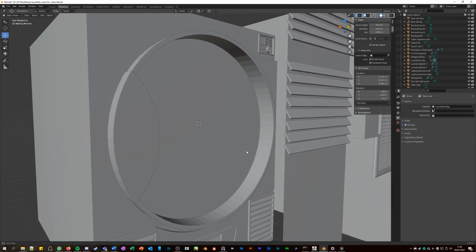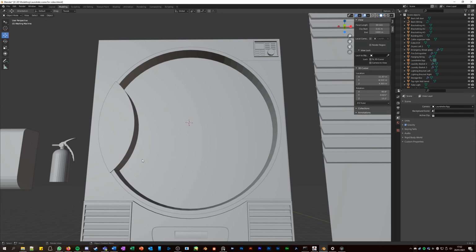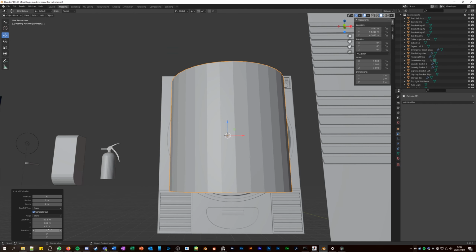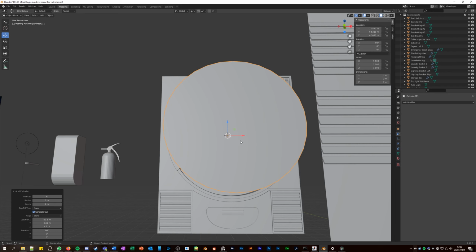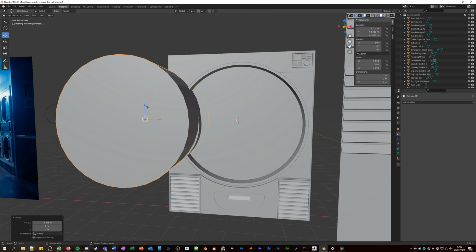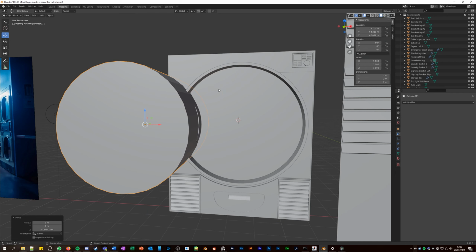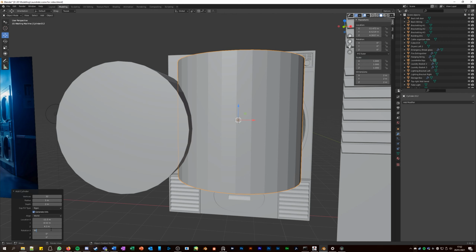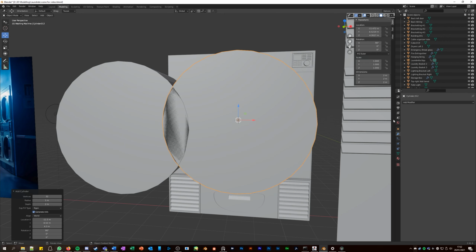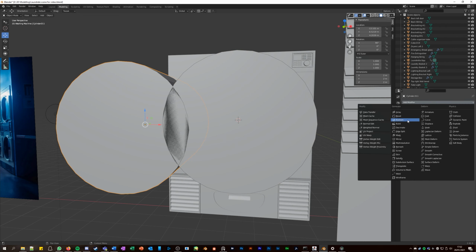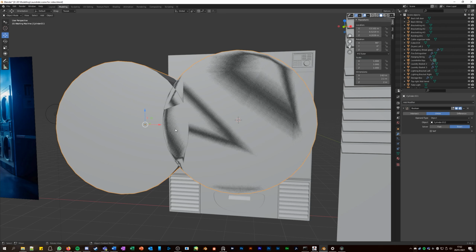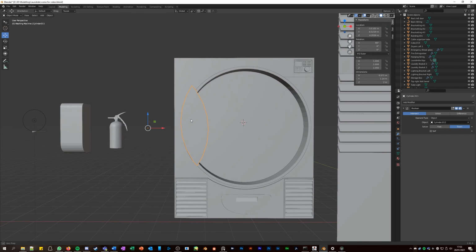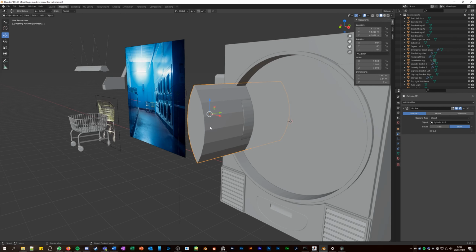And then I added this handle, which was another whole cylinder, which you can kind of see fits in, so 90 degrees. So a cylinder there that I then did a Boolean of this other cylinder. So bring another cylinder 90 degrees around the x-axis, and then did a Boolean modifier, but instead I did an intersect, not a union. So it brings this cutout in that's just the size of just that kind of rounded shape.